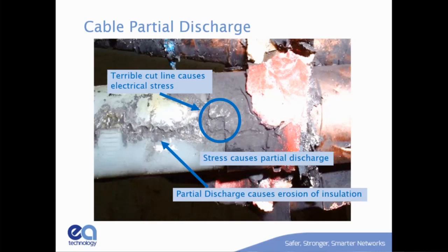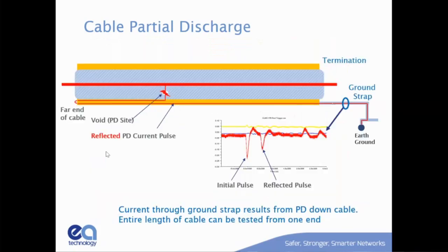If you see tracking on the inside of an insulator, I now have voltage at the end of those PD tracks, which could lead me closer to arc flash, right? If I've got voltage where I shouldn't, and then I move something, I could end up with arc flash.